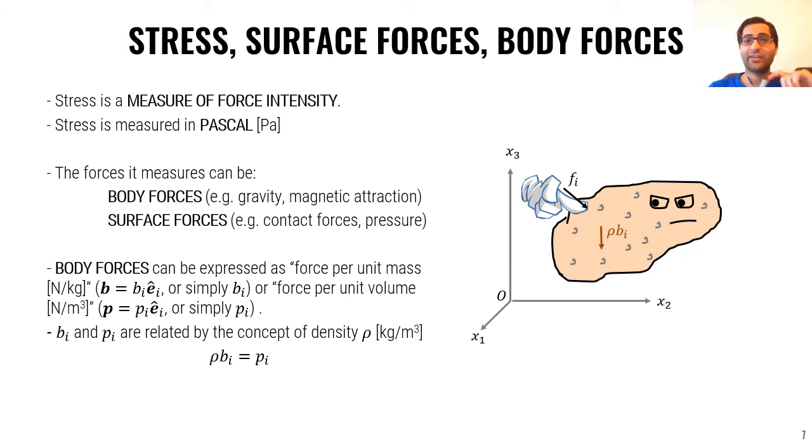Stress and its relation with surface and body forces. Stress is a measure of force intensity, and we measure it in Pascal. The force it measures can be body forces like gravity, magnetic attraction, basically any uniformly distributed internal force affecting the whole body. Here, for example, we have the gravity. Or surface forces like any contact or pressure that exerts the force to the body through the surface, like here.